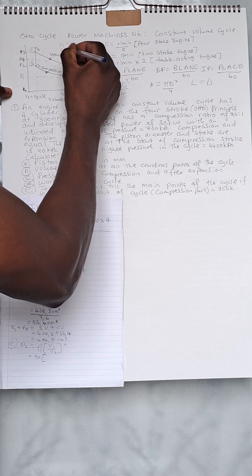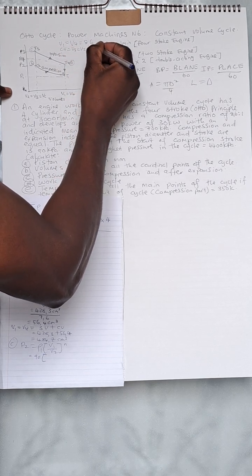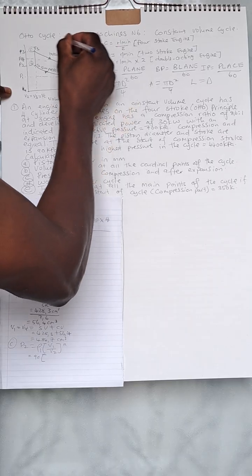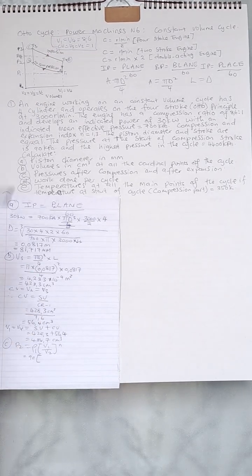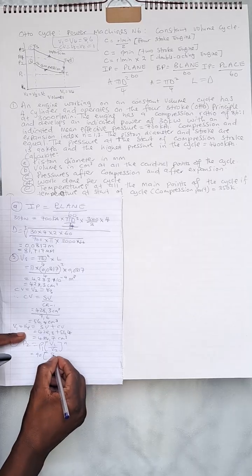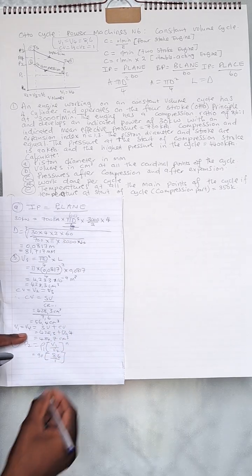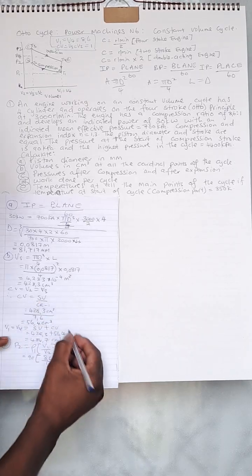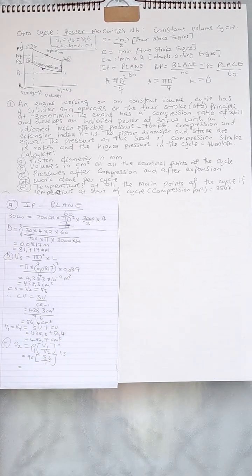But clearance volume equals V3 equals V2, which is equal to 1 from the compression ratio that is given. So our V1, it's 8.6. Our V2 there, it's 1. Our n was said to be 1.3. So let's see what we're getting as our P2.